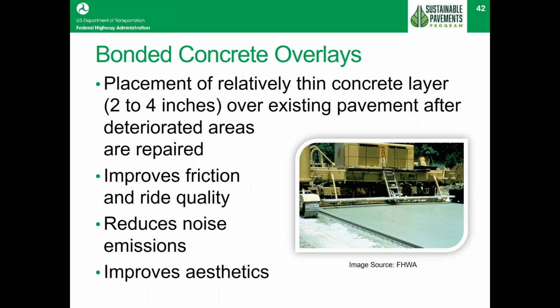Okay. Then we see bonded concrete overlays. Now, these are somewhat similar to the ones that we saw over asphalt, but this is where we put concrete over concrete, usually in a fairly thin layer. It's used usually where you have pavement that's mostly okay, but there may be some irregularities that are due to things like a utility cut.